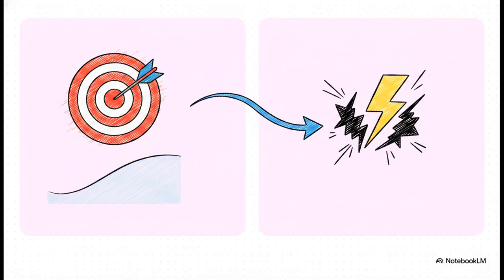To put it simply, let's contrast these two roles. The primary loop is your master process. It's relatively slow, and its main job is to set the reference target for the worker. The secondary, or inner loop, is the slave process. It's incredibly fast, and its sole purpose is to intercept those disturbances. Cascade Control architecture isn't just taking two controllers and letting them fight for dominance. It's a beautifully structured, highly efficient delegation of responsibility.